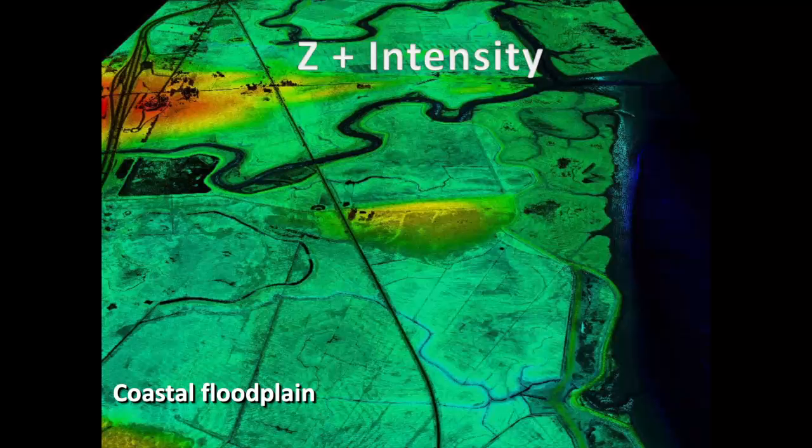And it's not just about elevations, it's not just about coordinates. What this image illustrates is we've got a point cloud, so we can see the color variation is the elevation of the point cloud, but then the tonal variation, or the brightness in the image, is actually the signal strength or the intensity. So we can simultaneously visualize the elevation content within the image, but we can also visualize the brightness of that image. And why is that useful?